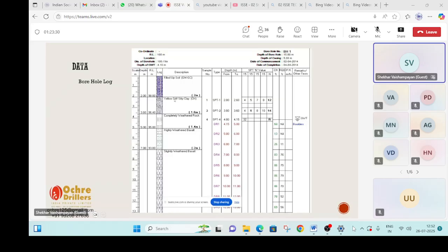So what are the different layers seen within the borehole? You can see a bit of soil. This soil is actually material brought from outside and deposited on the ground to level the plot, mostly. The second layer is the first virgin layer, virgin ground level, yellow stiff silty clay with some N values. You can say stiff because N values are more than 8, so 12, 14.